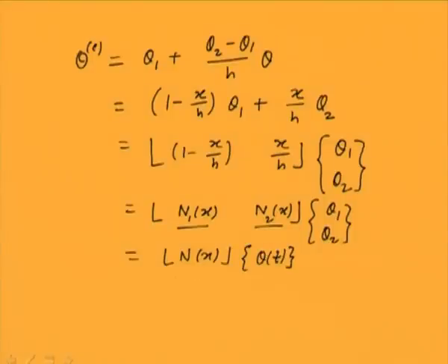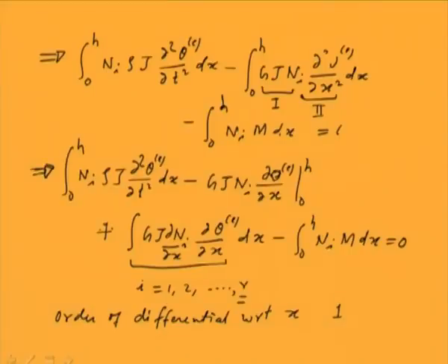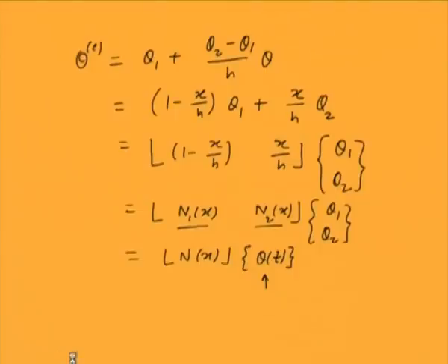So, here you can see that the shape function is a function of x, and the nodal displacements are functions of time. This solution which we obtain will be substituted in this particular equation which we obtained earlier. We can have r as 2 here, so we can have two such equations, and we are able to combine them. So, let us combine them. The combined form of the previous equation is this. We have combined two equations here, because this is a vector, N1 and N2 are there.